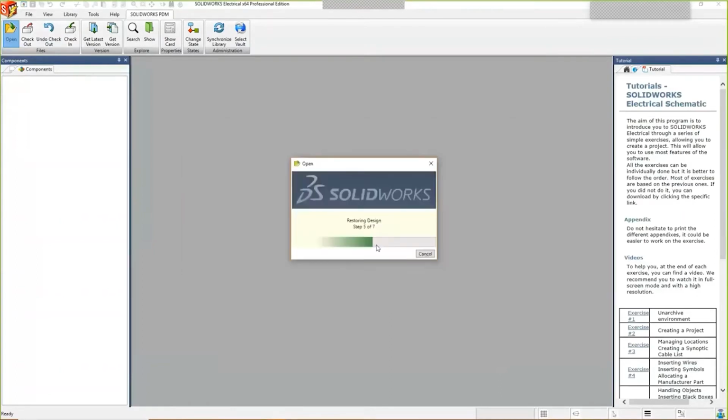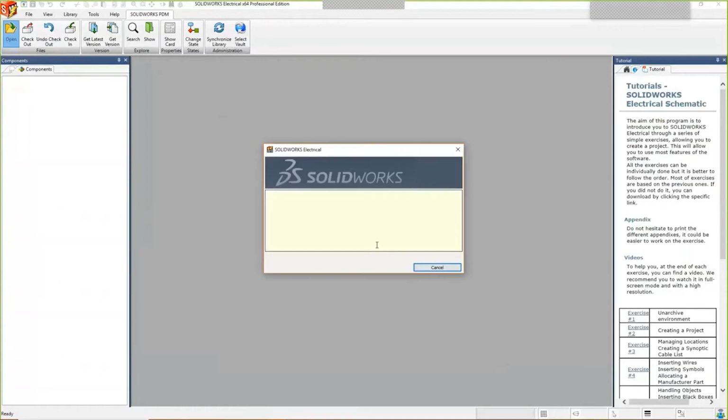So the other difference is that, just like if you're using the out-of-the-box PDM check-in, check-out functionality, there's a gatekeeper. So one person is the only person that can check things into the vault, right? Because the whole project is checked out by one person.